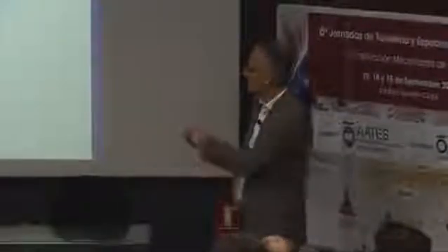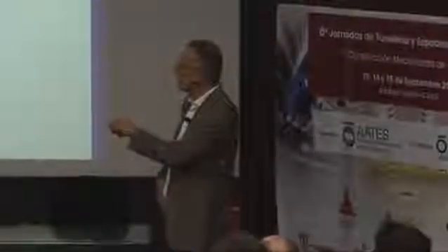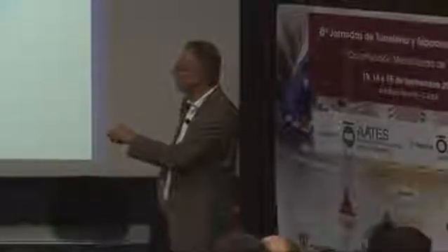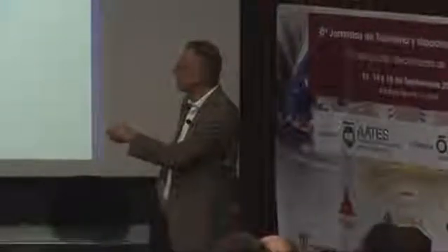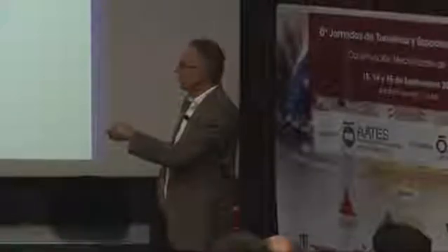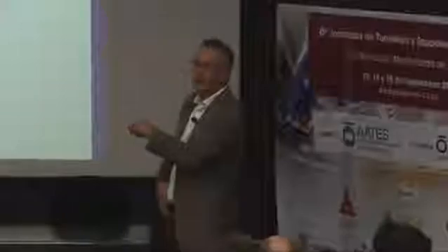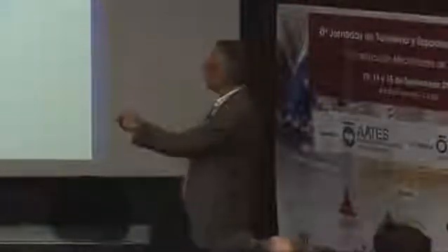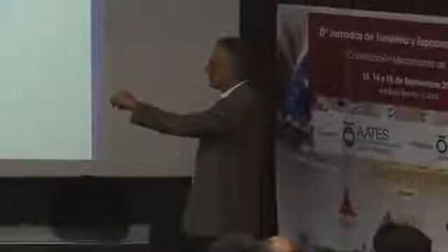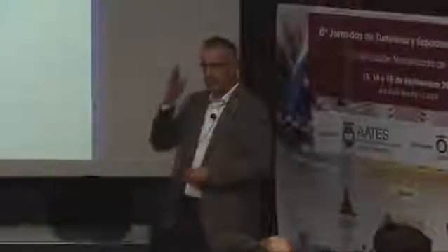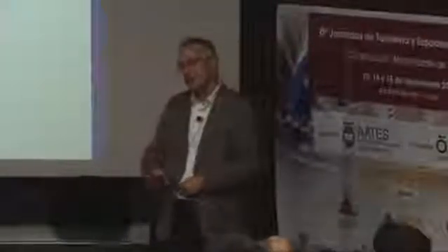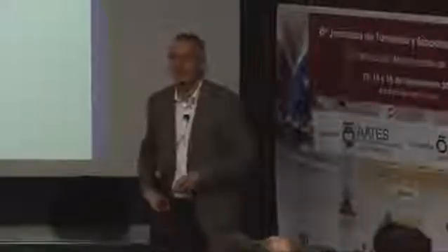What is happening then to your tunnel face? When we go back one step, you see here what actually holds and stabilizes my tunnel face is the pressure difference at the tunnel face between the surrounding ground and your active face support pressure level inside the excavation chamber. It's, during advance, as mentioned before, a quite defined line. That's where your step is, and that's how you apply the face support pressure.